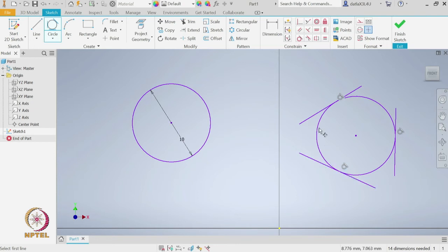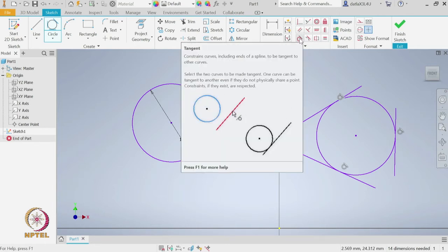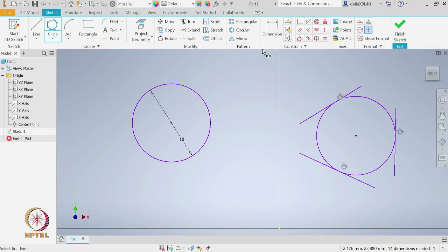You will notice that when it created a circle, it shows some symbols. These symbols are actually constraints. So, for example, this symbol signifies tangential constraint. It says the circle is tangent to the line here. Similarly, we have one more tangential constraint with the line 2 and another tangential constraint with line 3. If you look closely, we have this tangential constraint here too in the constraints option.